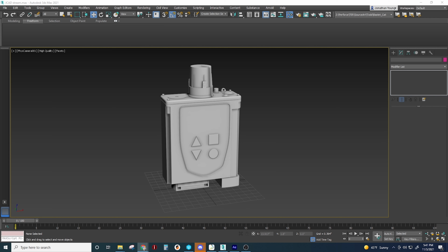So at this stage, I have to think about how this object will fit together after it's printed and engineer any points of separation at this stage. So we need to determine a few things. Does my model have significant overhangs that will generate a lot of support material? Because this could have a significant effect on print time and the amount of material used. Am I going to paint it? Should I print certain parts in different colored plastic?